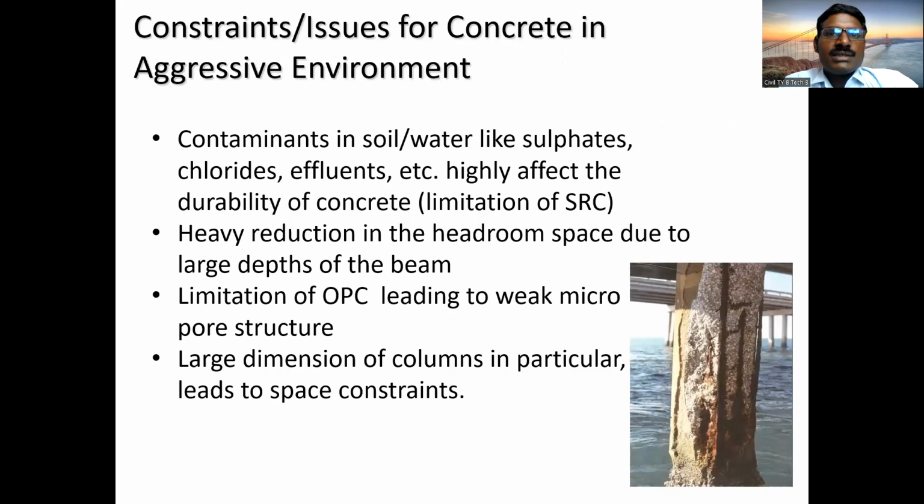So constraints and some issues for concrete in aggressive environments are contaminants in the soil and water like sulfate, chloride, effluent, etc., which highly affect the durability of concrete; that is the limitation of SRC.